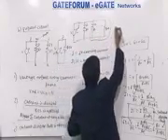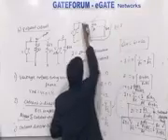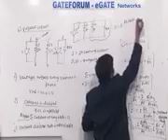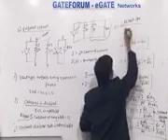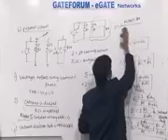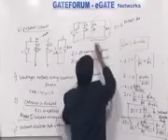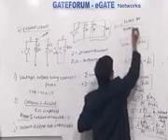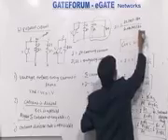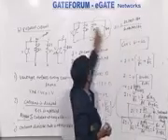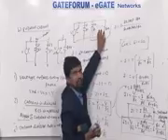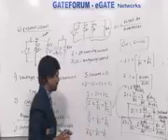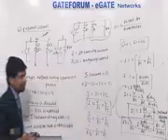So you can say that I1 is equal to the total current I into the opposite resistor, R2 parallel with R3 parallel with up to Rn, divided by R1 plus R2 parallel with R3 parallel with Rn. So the current flowing through I1 is equal to the total current into the opposite parallel combination, that is the opposite resistor, divided by the sum of resistors. So we can say that the current division rule is applicable.